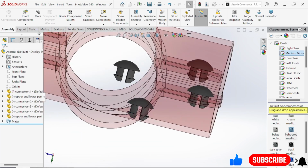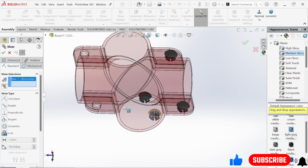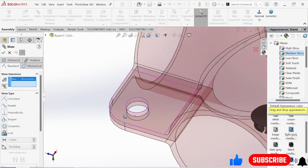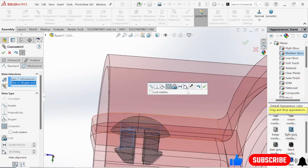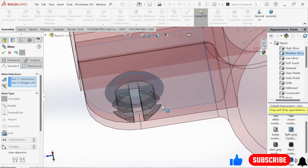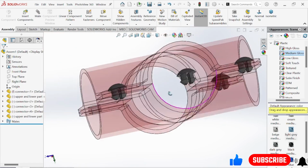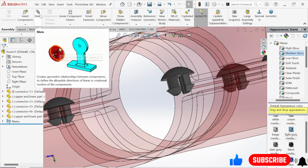Let's assemble this thing again. Again go to mate, select the surface, select the external surface on which you are going to mate. Always remember that you only have to select the surface which you are going to mate. Simply select the line, it comes exactly in the middle of it. Now come here, select this surface, select this surface and make this one okay. Now here you see, and simply make this one okay. You have to do it again and again. That's why it is the complex part. It's the most difficult thing.